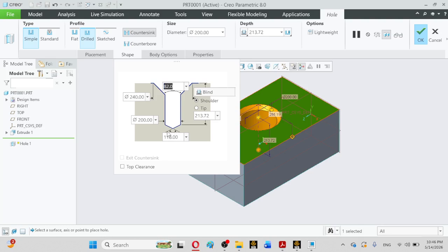As you have already observed, this is the drill bit angle. These are all the types of the drilled hole: countersink and counter bore. Means the subtypes for the drilled hole are counter bore and countersink hole. Remember, if I click on the counter bore hole, the countersink will not be deselected. So let us first deselect the countersink hole, otherwise a mixed-up hole will be created.